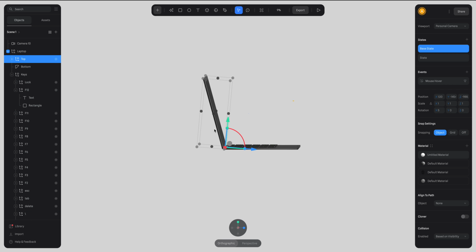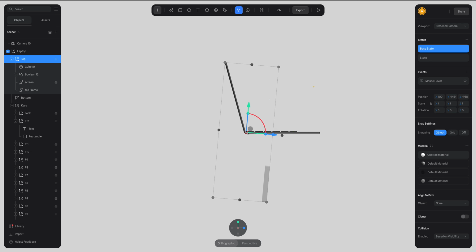So in order for that to happen, you have to create another object. Let's see if I can find it because I turned it invisible. There you go. So you can see that right here. So I hope I explained that well. So essentially, me creating this object right here and placing it where it's placed allows me to make the focus point of the rotation be right here. So as you can see, it places that in the center.